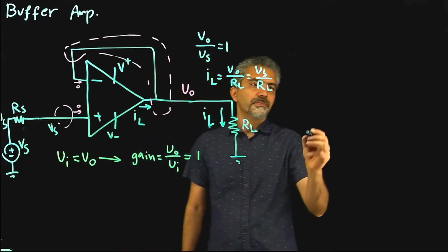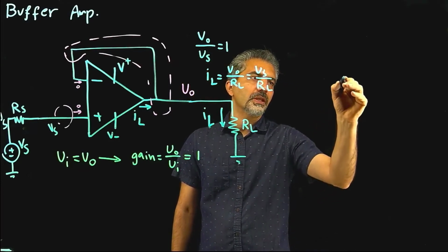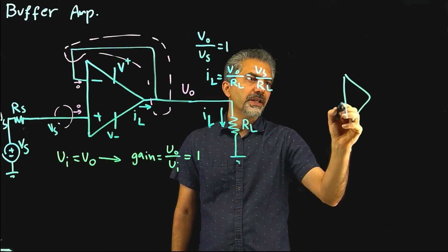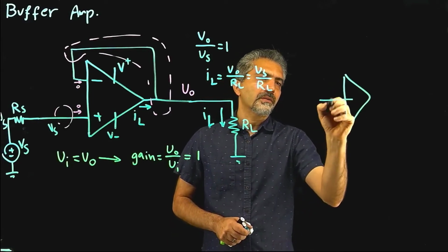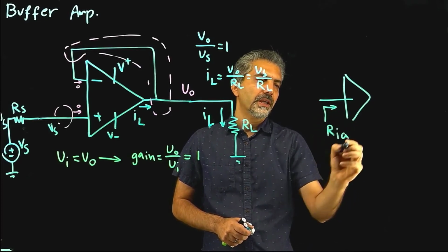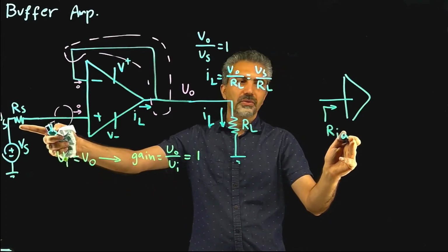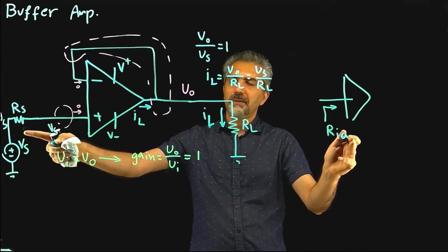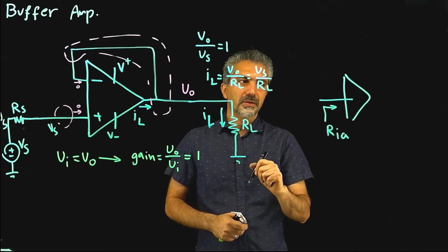So in other words, even if you're using an amplifier, if the internal resistance of the amplifier, we call it Rin of the amplifier, is not too large, then you end up getting into the same situation where the voltage divider happens and you lose signal.